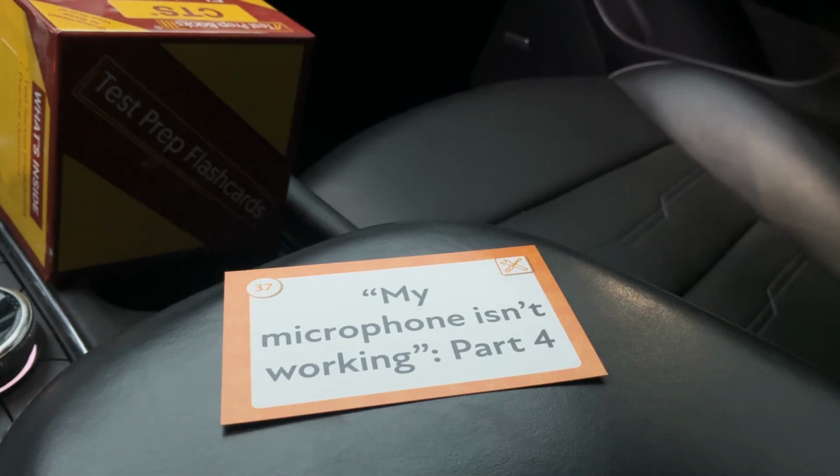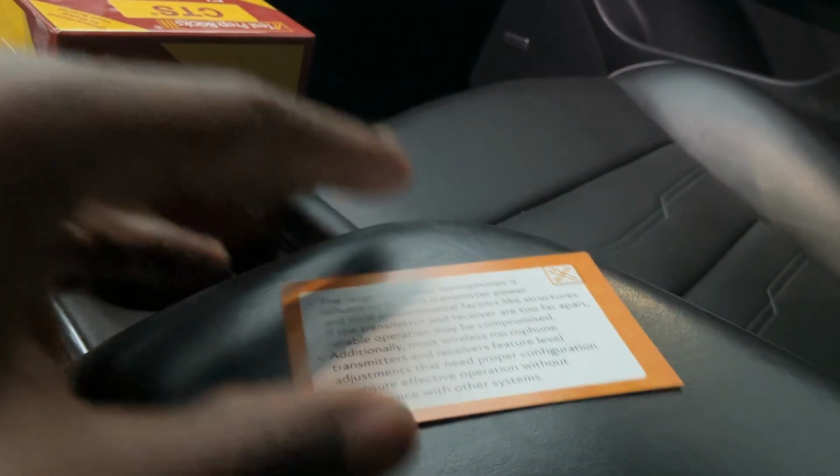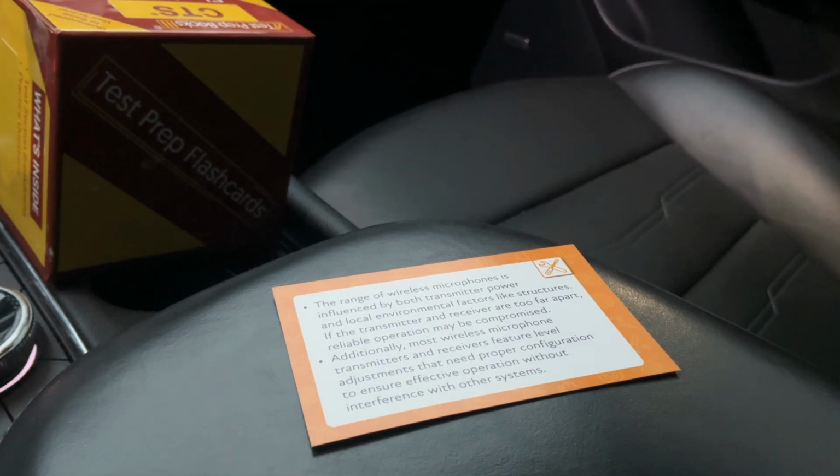My microphone isn't working. Part 4. The range of wireless microphones is influenced by both transmitter power and local environmental factors, like structures. If the transmitter and receiver are too far apart, reliable operation may be compromised. Additionally, most wireless microphone transmitters and receivers feature level adjustments that need proper configuration to ensure effective operation without interference with other systems.